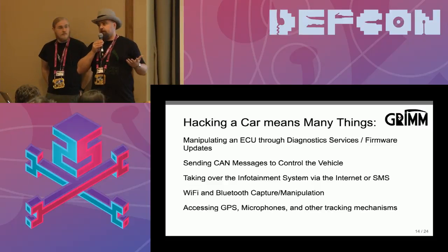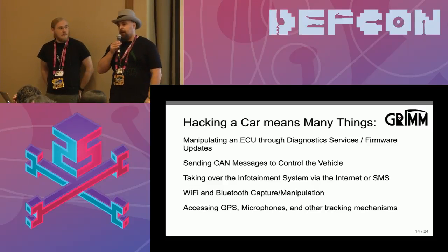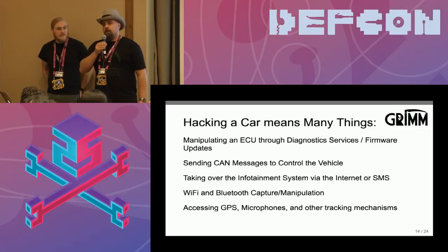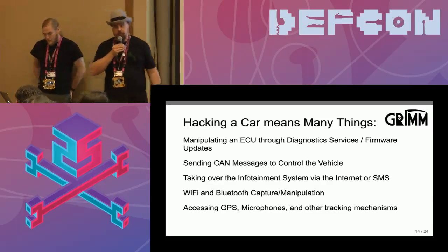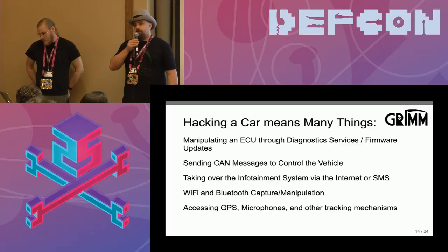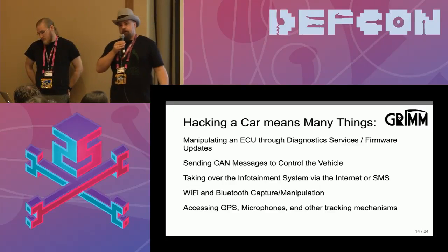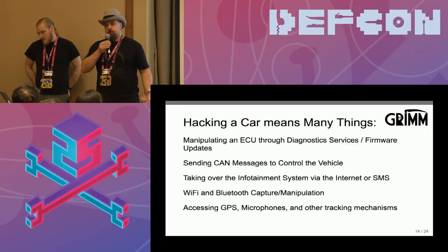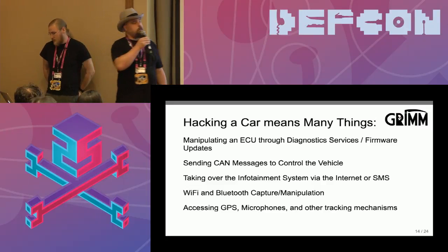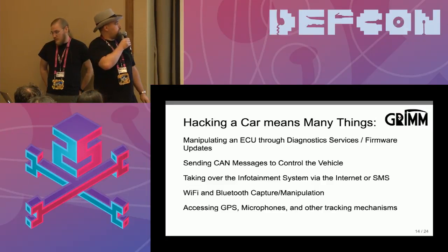Now, the segregation is actually happening, and we're seeing it happen in the real world: the infotainment, which used to maybe be on every CAN bus, is now only on a couple of them, which is great, especially isolating it from the safety critical systems. So now you still have to pivot off something, because there are things that are connected to both CAN buses. We've got to find a device that's also vulnerable to compromise to pivot onto the bus that you want to get to.